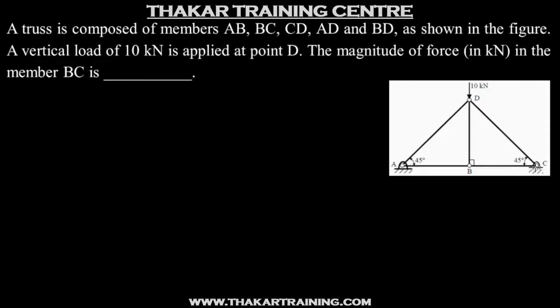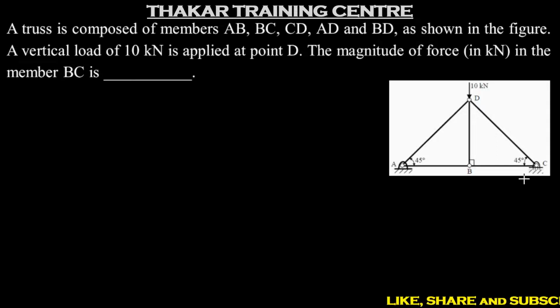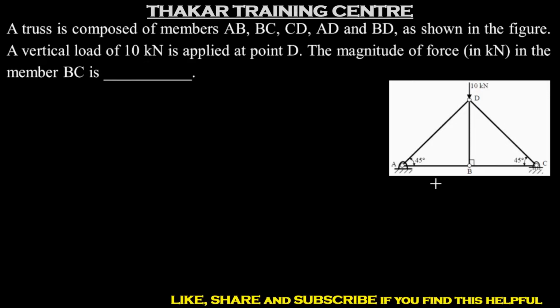If you look at joint C, we have two members and we will have one reaction. So at joint C, we will have three forces. So we will be able to apply Lami's theorem at joint C. But before doing that, we will find out the reactions.